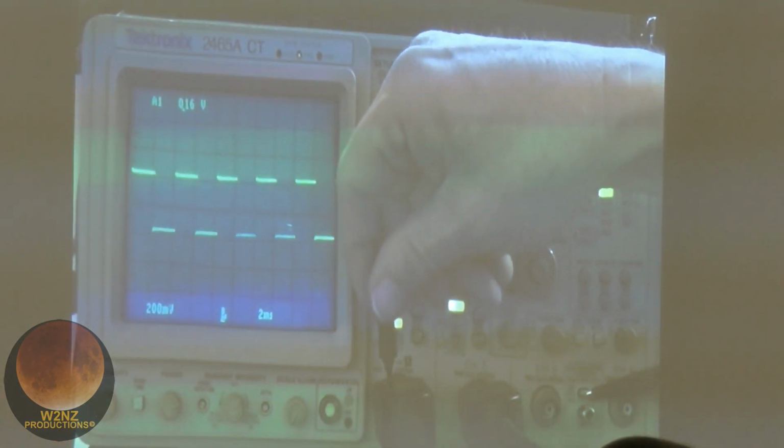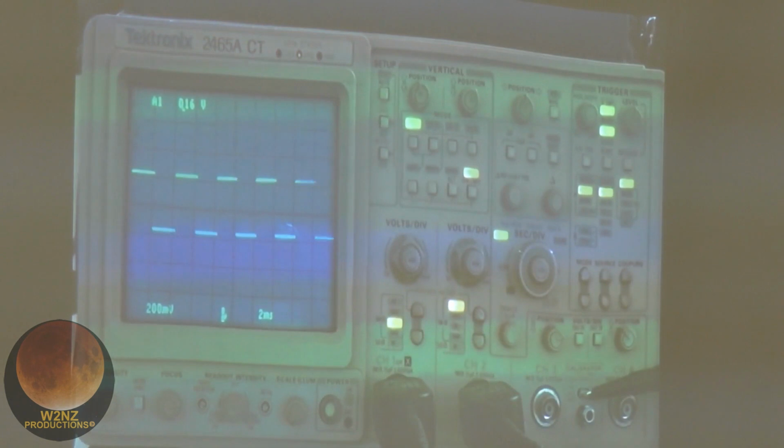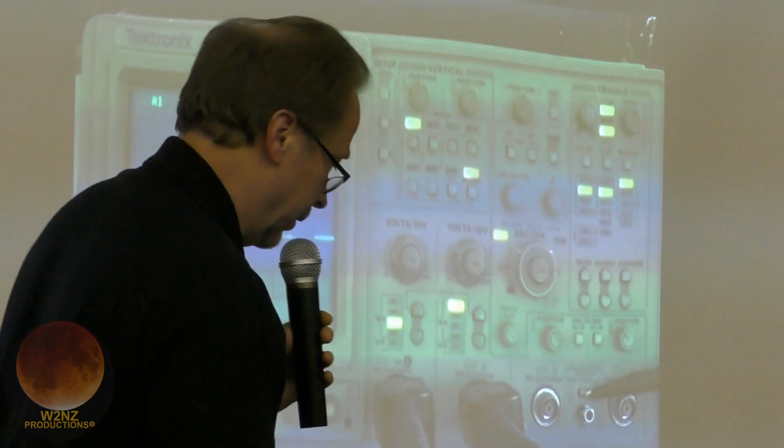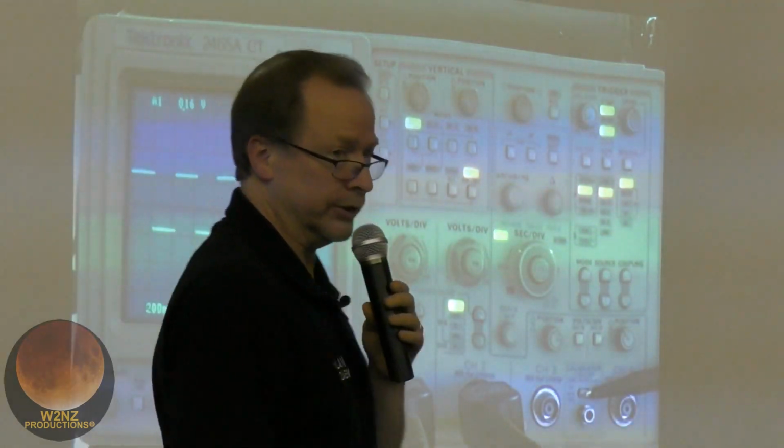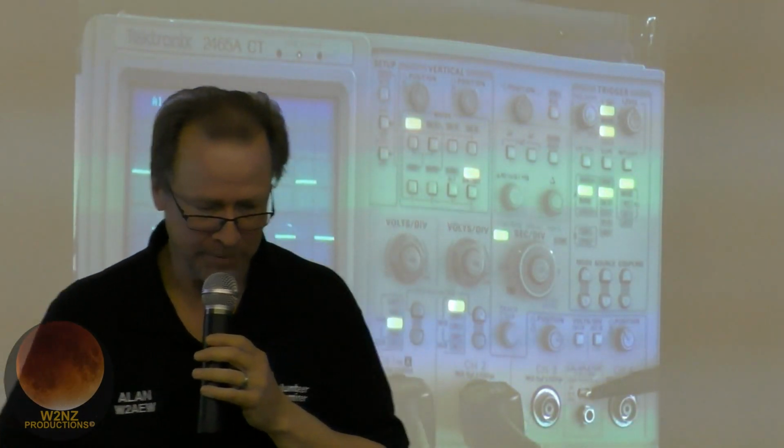go compensate your probes. Hook them up to that probe compensator input and adjust that capacitor so that you flatten out and make it look like a perfect square wave. That's probe compensation. Something that's really important if you want accurate measurements, and so many people don't even know what that is. Okay, but it is a kind of an important thing.